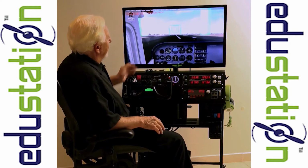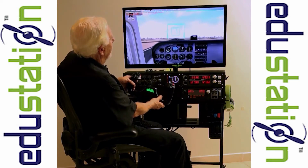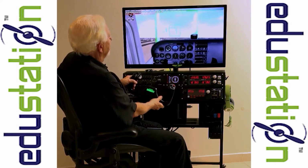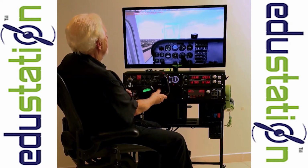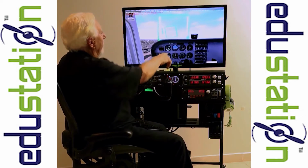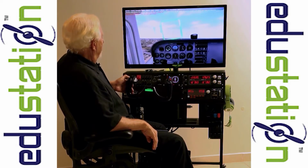And when we achieve 60 knots, we're going to gently pull back, and we're going to fly directly into each of the boxes. Continue climbing to 700 feet. Upon reaching 300 feet, retract the flaps. The good climb-out speed is about 75 knots. So it's basically a straight climb out to about 500 feet before we're going to do any maneuver. And so we're climbing now.